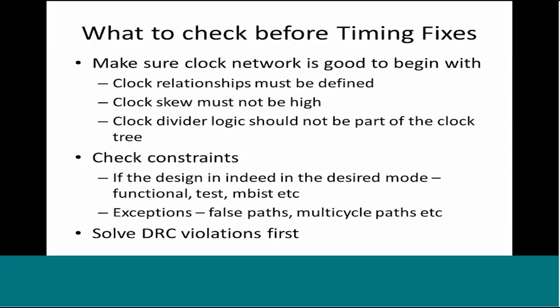So I'm assuming that either you yourself or somebody else is giving you the post layout data. Post layout data is netlist plus SPEF. Now in the industry, many times it may happen that the backend tool used for post layout, that is for placement and routing, is not a Synopsys tool.